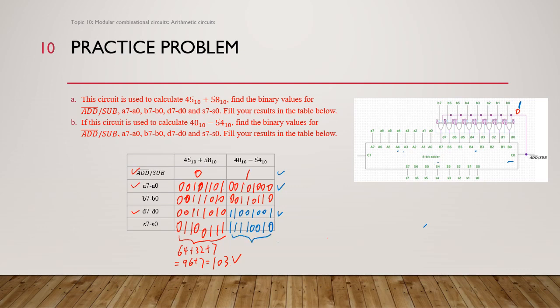But how do we know this is the right answer? Again, because this is a sign bit, this is a negative number. So we cannot tell the magnitude directly. We have to do the 1's complement first, then plus 1 to get the 2's complement. Okay, now we can know the magnitude, which is 14. So this number represents negative 14. Is that correct? Yes.